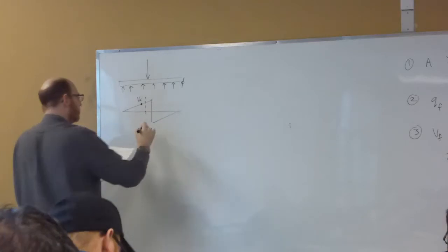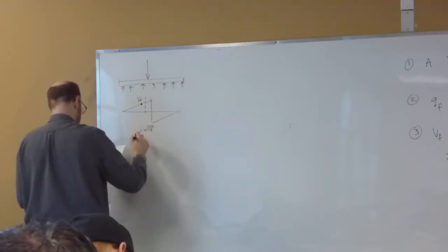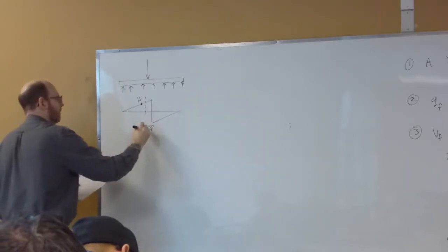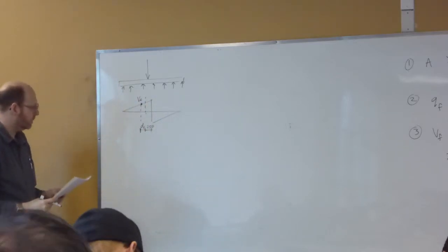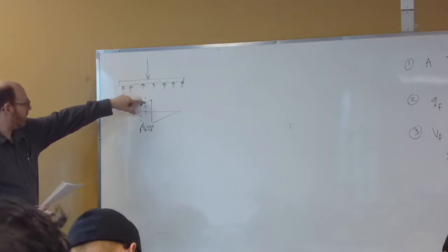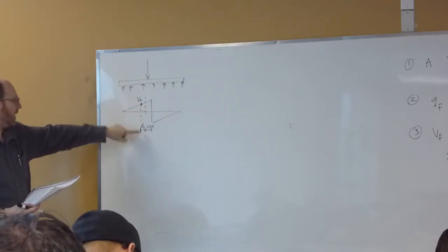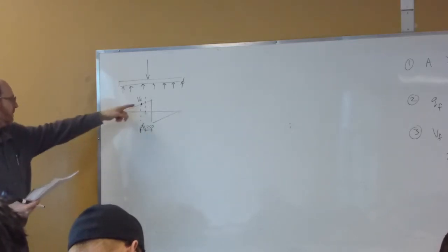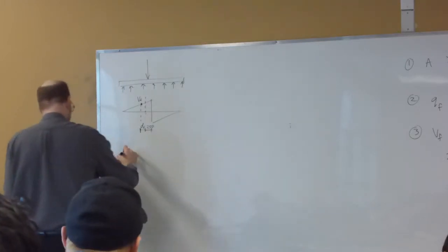We had 500, so this is 250, and then this distance here is dV. Again, this dashed line here represents the edge of the column, and we're going away from the edge of the column another dV value. So what I want to do is come up with the value for VF, and this is just based off of similar triangles.